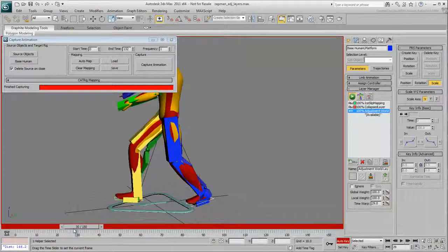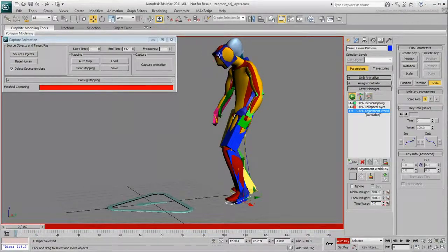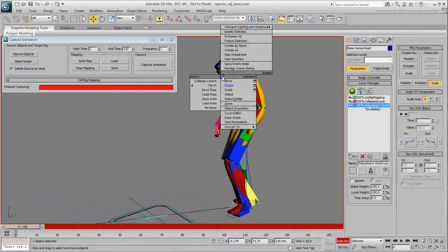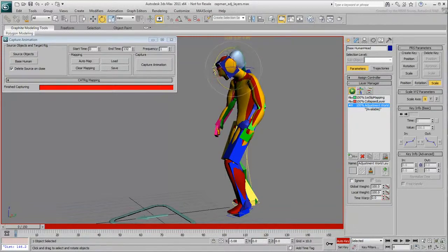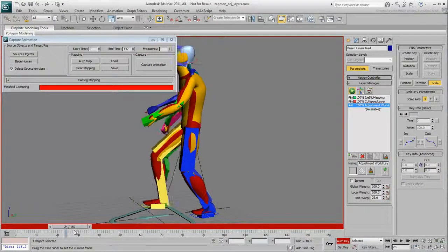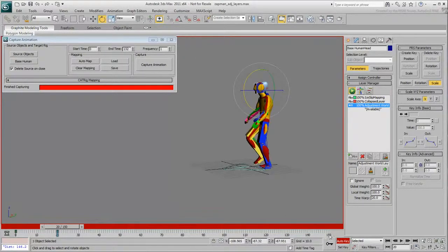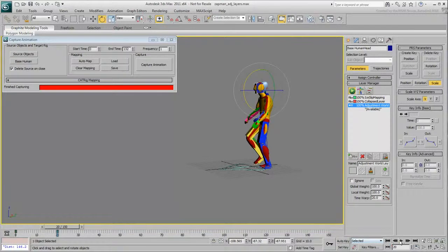The underlying animation is still intact. Similarly, make small adjustments to the head and chest at frame 0. Make more adjustments at other frames if you need them. Possibly a slight adjustment of the head may be needed around frame 20. Disable Auto Key when done.